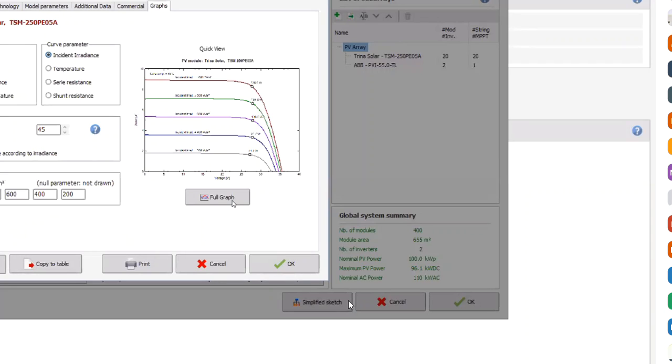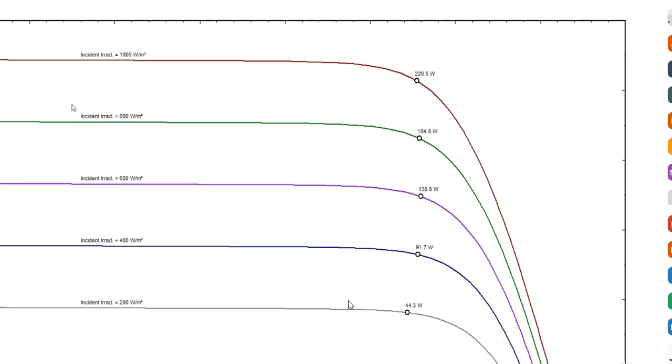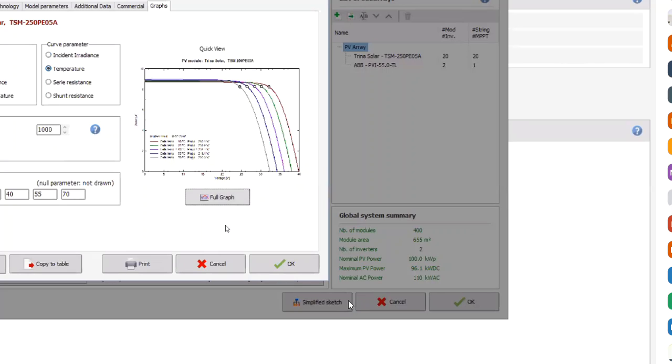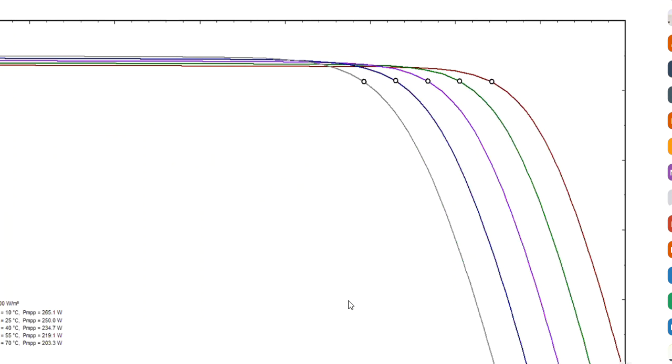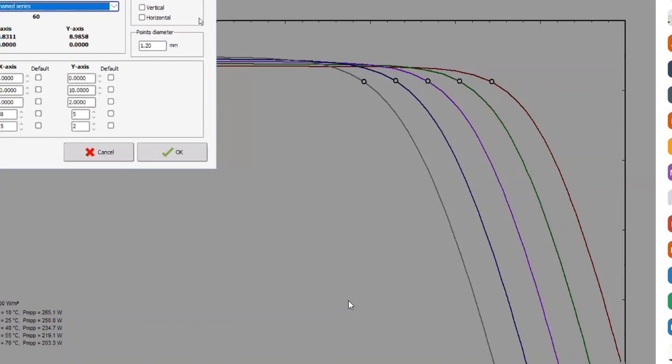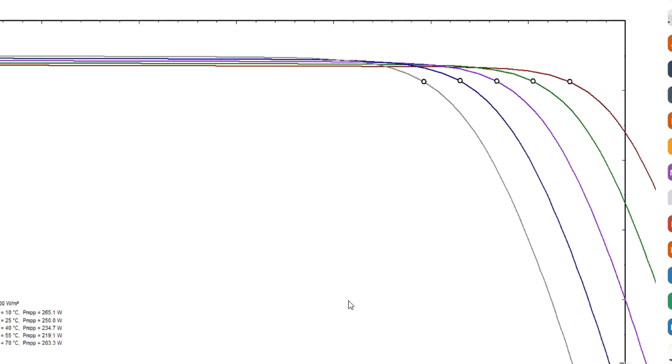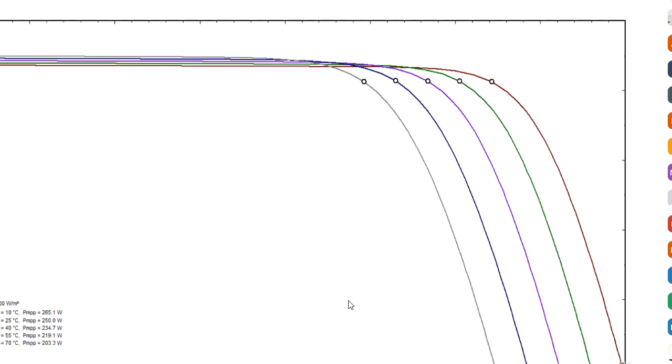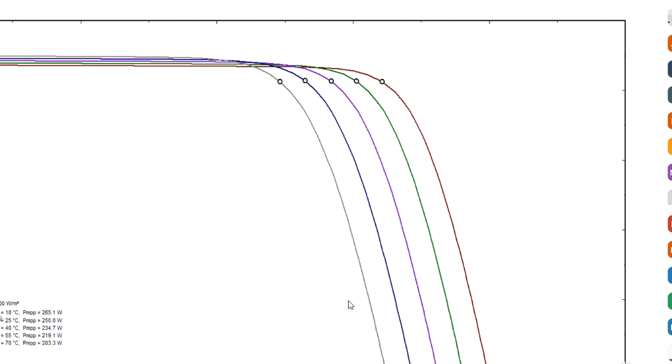If you go to the graph, you can find this type of criteria. This is the radiation. Now I just understood. The doubt was whether companies manufacture as per the requirement of that particular area, how much radiance there is, and how much temperature persists at that place. So this is the graph. At 10 degrees centigrade your wattage is 265. At 25, the STC condition, it is 250. If you go beyond 40 degrees, the wattage will again reduce. So you can find this type of thing.